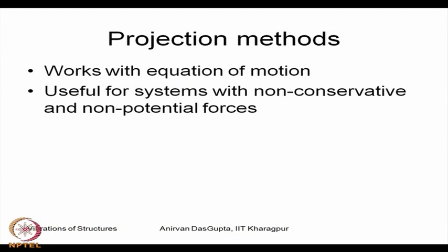Since these methods work with the differential equations directly, they can be used very easily for dealing with non-conservative forces, non-potential forces, etc. These terms can be directly written in the equation of motion, and they are a little tricky to introduce in the Lagrangian as such, though it can be done that way. But if a method works directly with the equation of motion, then these non-conservative terms and non-potential forces can be handled quite effectively.